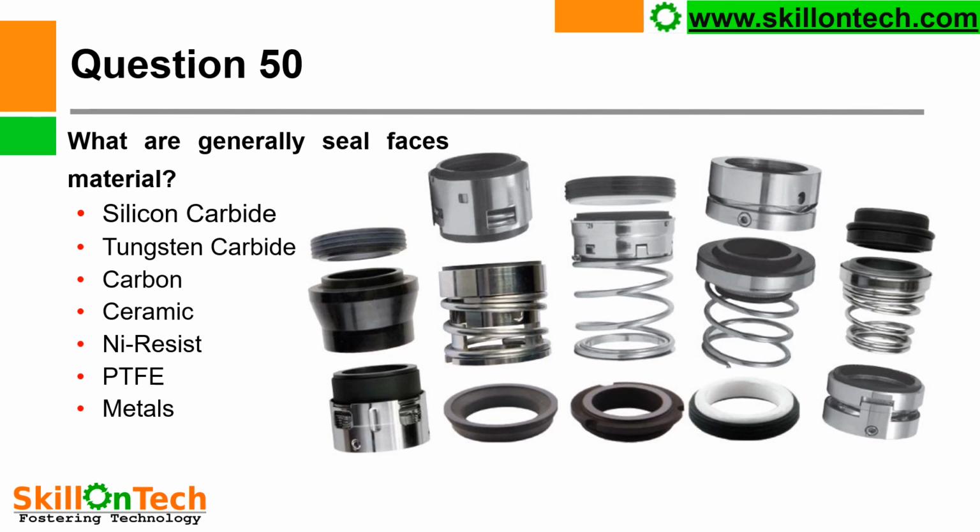In mechanical seal, there are two seal faces. One is stationary seal face and other one is a rotary seal face. The stationary seal face is always made of softer material compared to rotary seal face. In case any foreign particles occur in the seal face, then that should be embedded in the softer seal face. So seal will even though work.